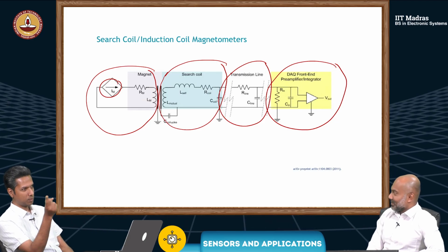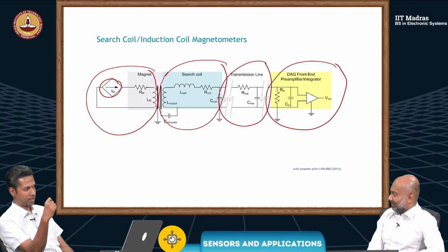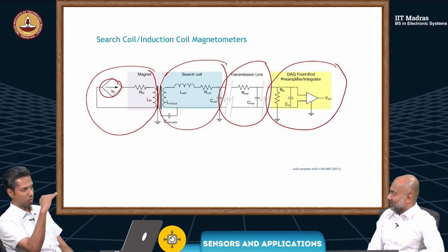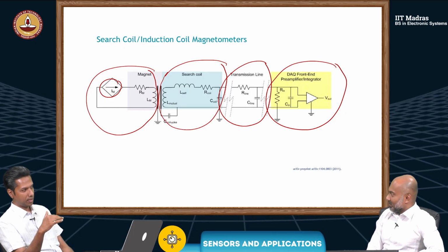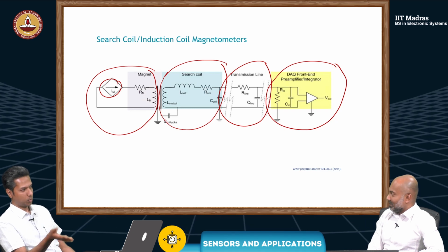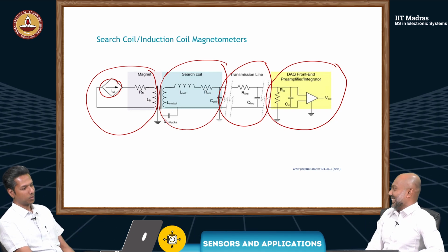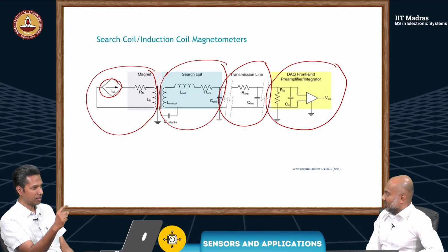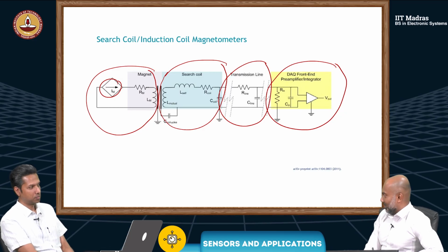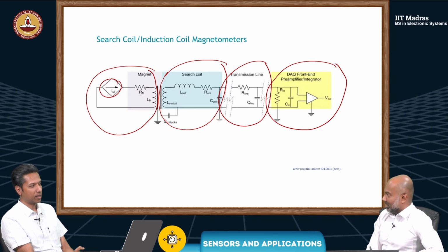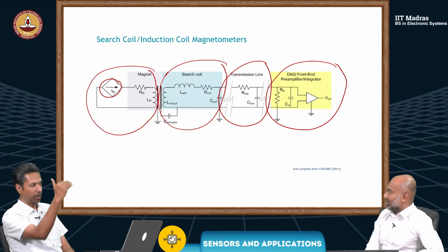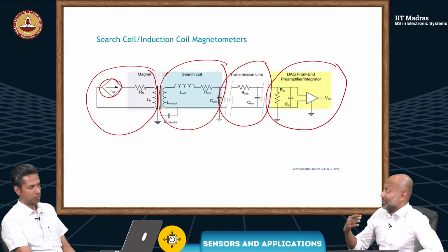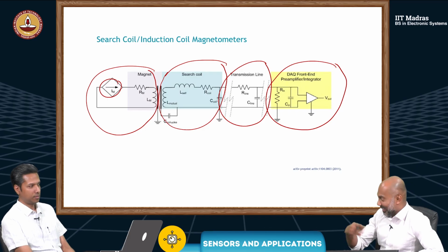True. So you have conductors stacked, and they are insulated from each other. Yes. So if you take 2 turns, they are separated by an insulator. So you have a capacitor. For an entire coil, maybe we can represent it as a lumped capacitor. Lumped capacitor. Correct. Although they are distributed between each turn. Yes, because you could have a number of turns, and on top of that another layer. You could have many layers.